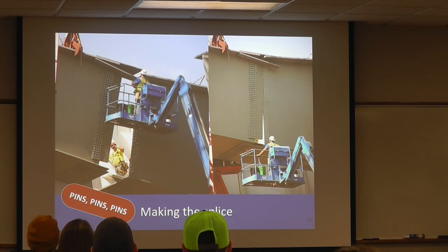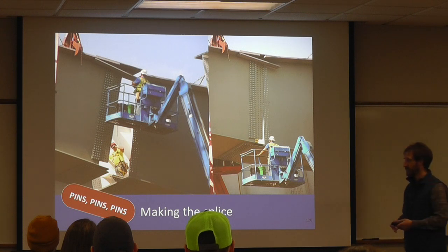Again, here they pre-stuffed a lot of these holes. This particular splice, this is the GIB 52 in St. Paul. This one I think has 600 bolts in it. So not a small effort to go through it and tighten all that. We do require, and this one, very much so lacking on this side, we do require pins. So this is a drift pin.